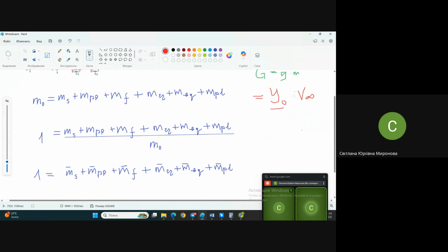You do remember that in case weight is known, lift equals the weight, and speed we know, it means we are able to determine the area of the wing. The area of wing which is not designed yet. The area of the wing, the area of the stabilizer, the sizes of the wing, and so on, in case we know the weight of the aircraft. But how may we know it? We haven't designed it yet.